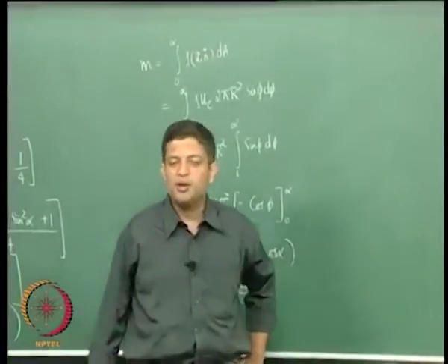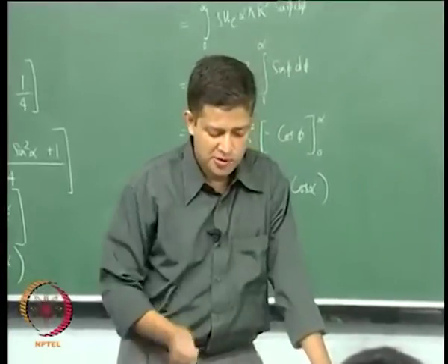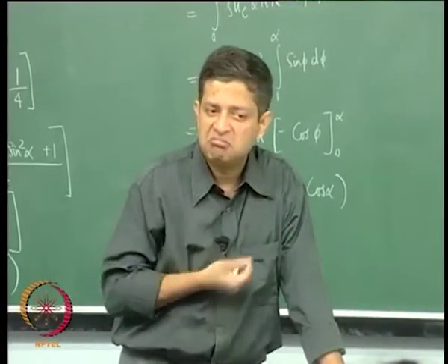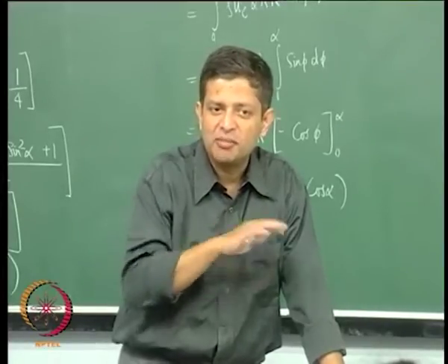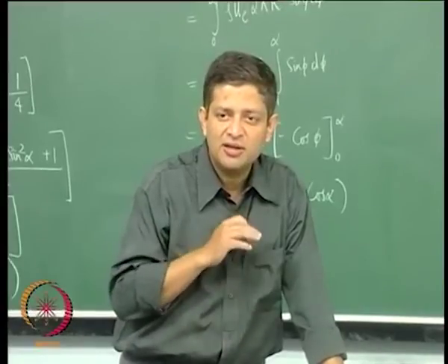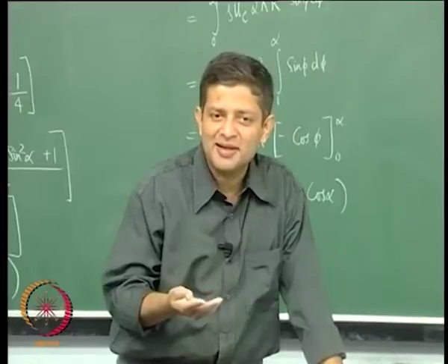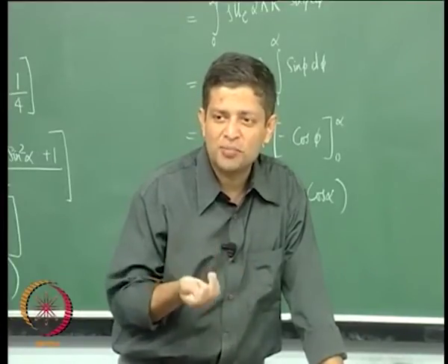Now, how do we minimize this thrust loss? One way to look at it is make this exit angle very small, right. Making this exit angle alpha 0 is impossible, because 0 would mean that you cannot have a supersonic portion at all.